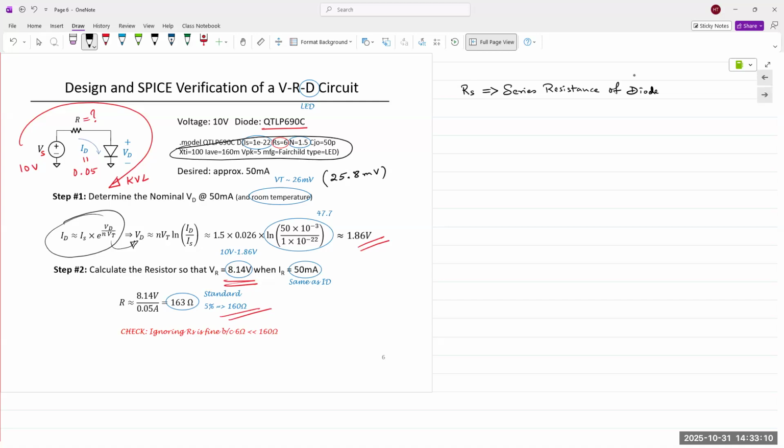So there's junction capacitance, there's transit time, TT, CJ0. There are a few other things in there. But for the most part, we ignore the RS if you are doing any calculation, and then we just run it. But here, we're ignoring it to actually make a point. And we will see that point in just a couple of slides. So everybody get that, the question and the response? Okay.